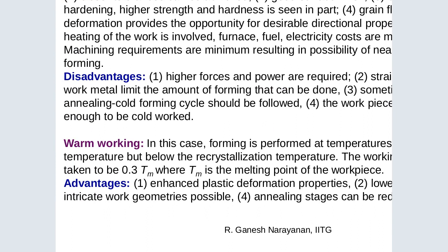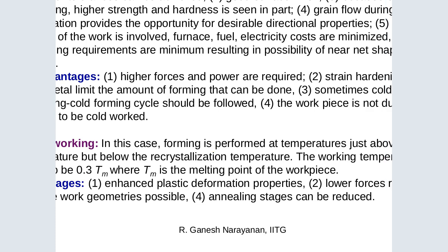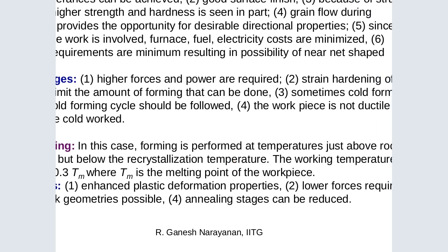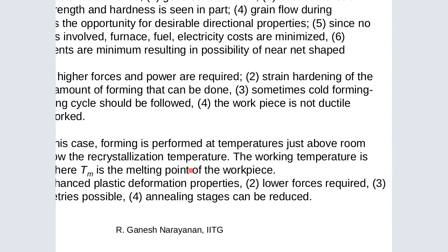So what are the disadvantages? It needs higher forces, because you need to apply a lot of force to deform the metal. So a disadvantage of cold working is that higher forces and power are required.